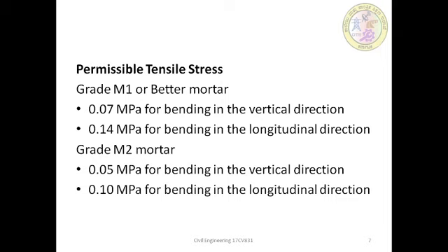Now, as a general rule, the design of masonry shall be based on the assumption that masonry is not capable of taking any tension. However, in case of lateral loads normal to the plane of the wall, which cause flexure tensile stresses, for example a panel or a curtain portion and the freestanding wall, then the flexure tensile stresses may be permitted in the design for the masonry.